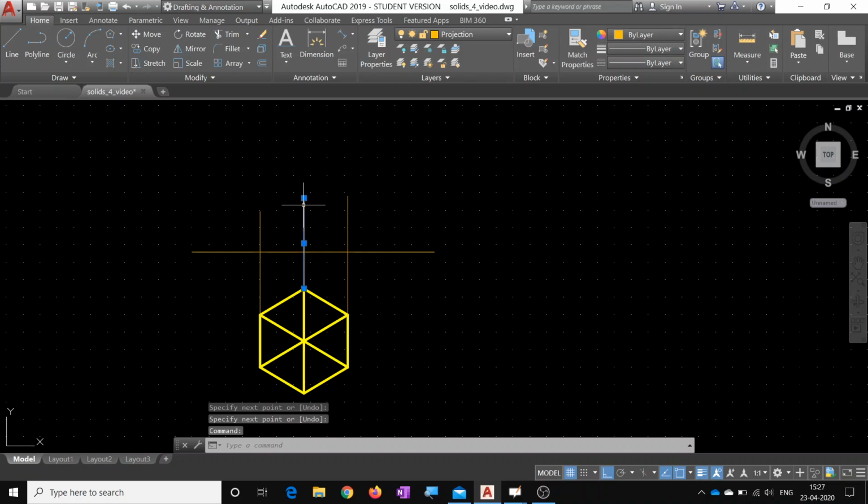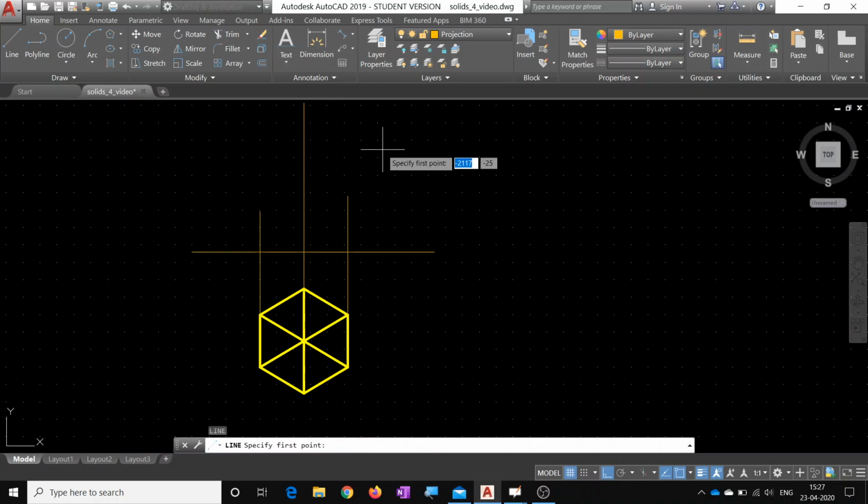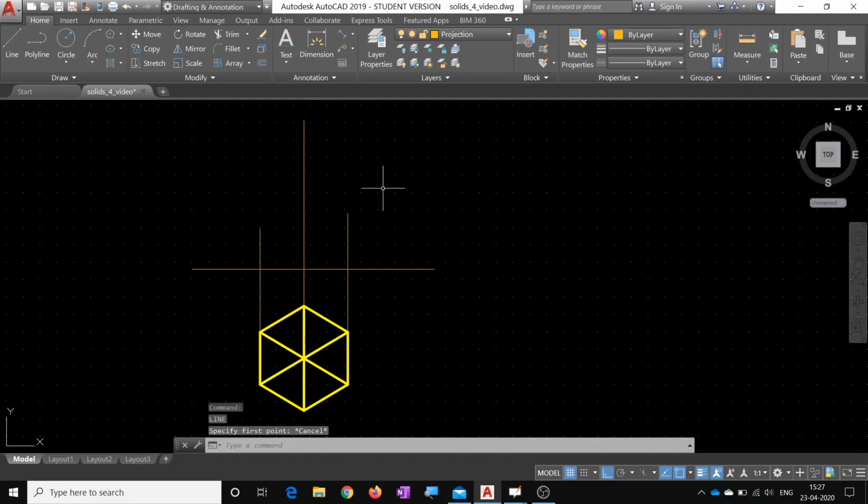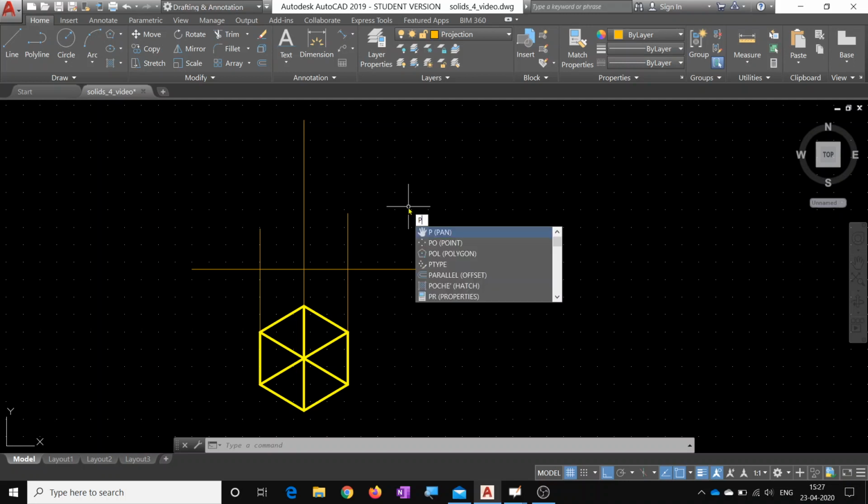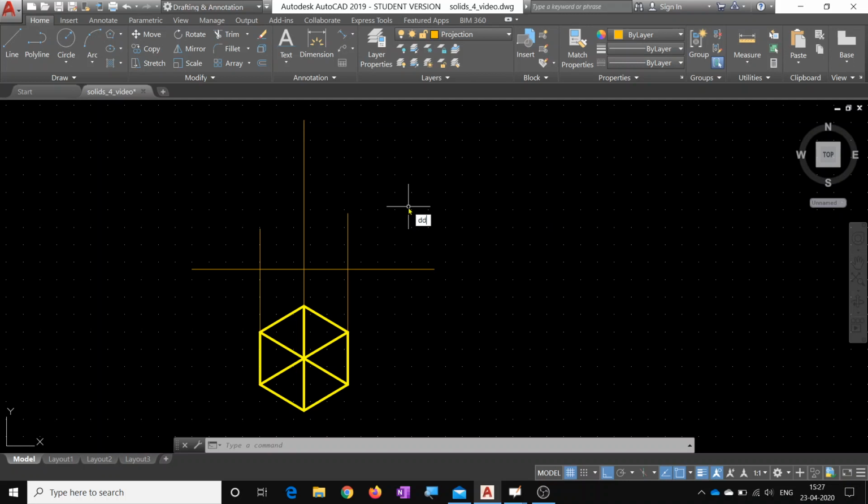You can see that this can be extended a bit because axis height will be taking on this. Okay, now what is the axis height? It is 100 mm. So for that you need to indicate that with a point first, mark it with a point. So you need to set the point type. For that the command is DDPT, DD point type, define point type, enter.